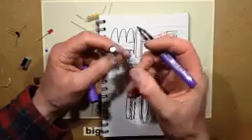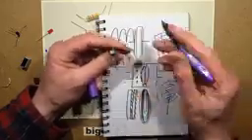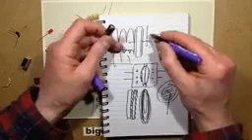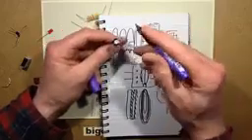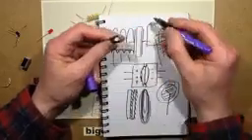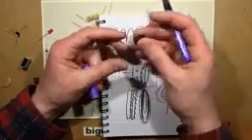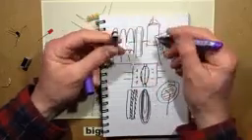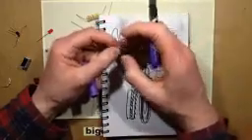Basically it turns into a sort of resistor, and it boils the electrolyte. And when that happens, the top will, if you looked at it from the side, bulge up. But if it goes too far, that X that's etched onto the top will split open, and it will vent out the top. And the other option, if it doesn't do that, is sometimes it blows the whole can off, and it just makes a mess.